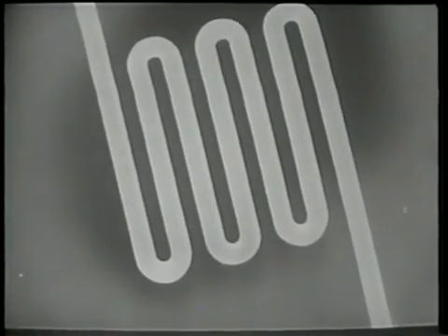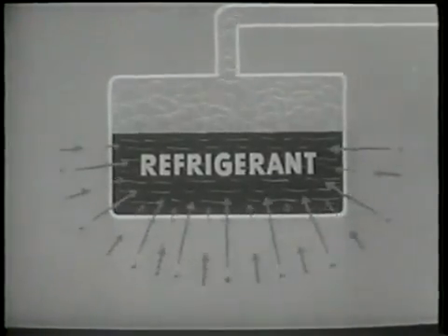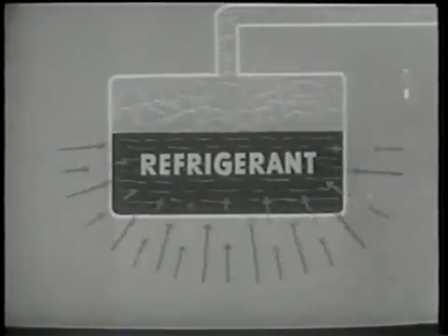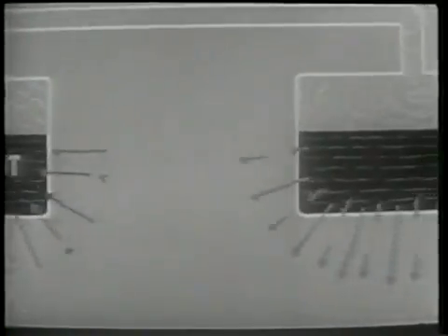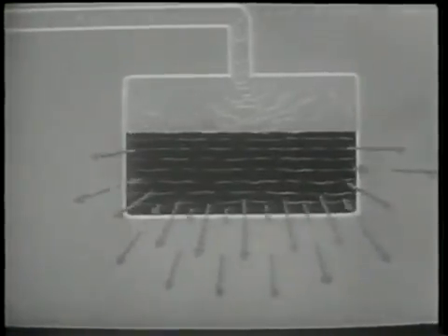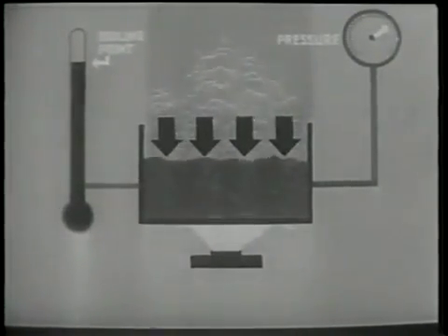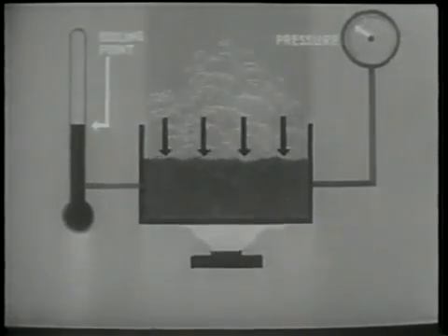The principles of refrigeration are physical principles applied as follows for the purpose of removing heat and reducing temperature. First, mechanical refrigeration rests on the ability of a refrigerant to absorb heat while changing from a liquid to a gas and to release that heat while returning to the liquid state. Second, when the pressure on a liquid refrigerant is reduced, the liquid boils at a lower temperature.